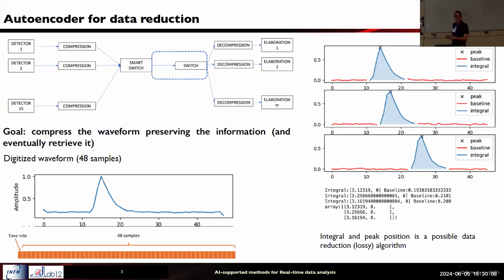So you have to guess out of the waveform itself where the baseline is. Baseline is usually due to a continuous current entering in some way, picked up by the detector, picked up by the electronics, whatever it is. You may have this level that fakes your data if you just calculate the integral. So the usual way is you subtract this line here. What you do is take a part out of the peak region and say my baseline corresponds to a certain value. So I take my sample.